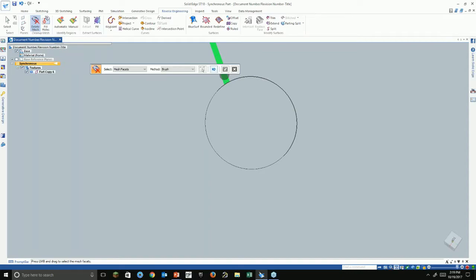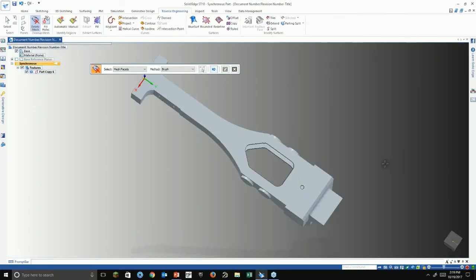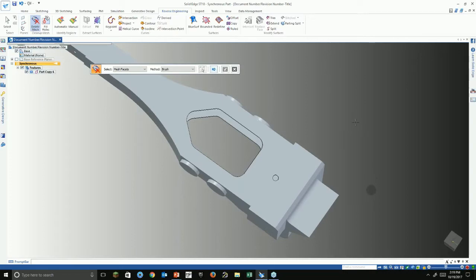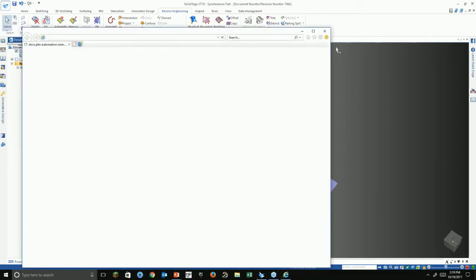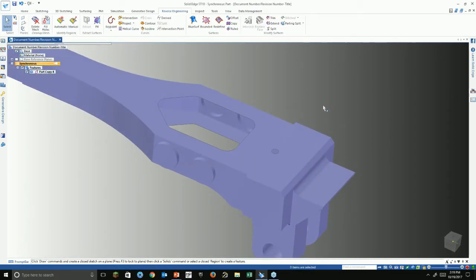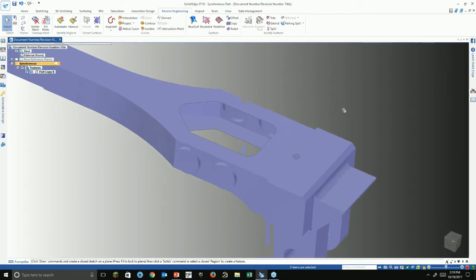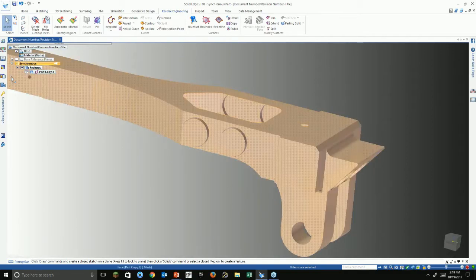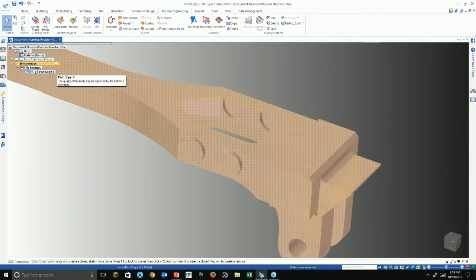The next tool I'm going to show you is actually something that's very useful. It's not just necessarily for manipulating, but if you want to print your STL, you typically would need watertight geometry to work with. So what we're going to do here is fill these in, and this could be done on an STL that you didn't necessarily modify. It just may have a missing surface that you can let this tool work with. All right, so you notice what happens here. Once I accept that, it actually turns that solid body into surface bodies.